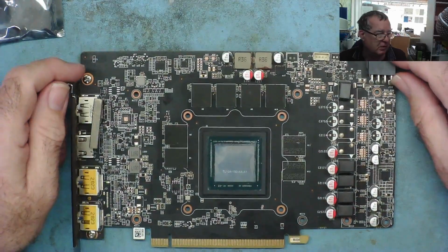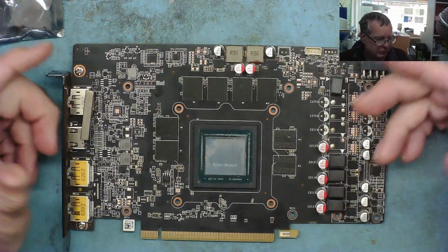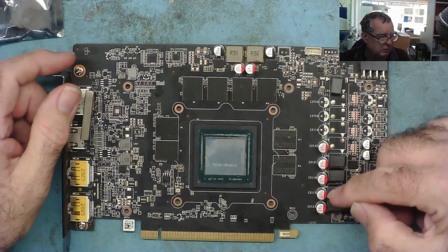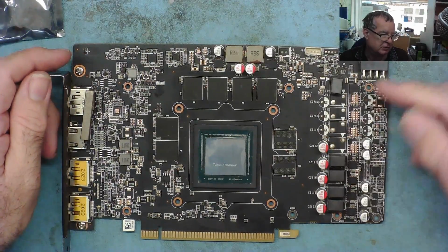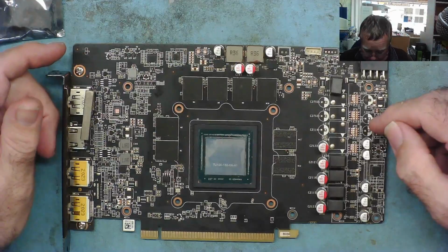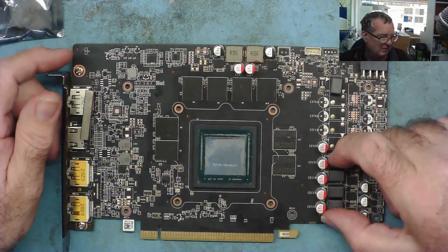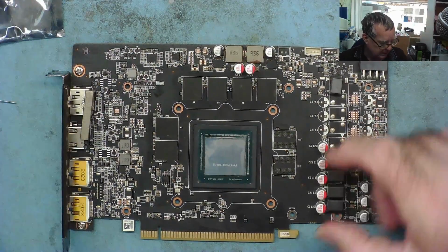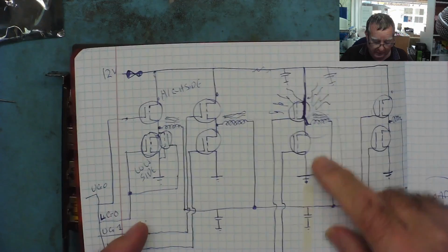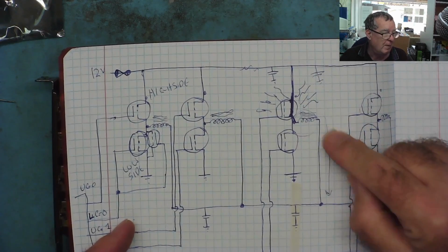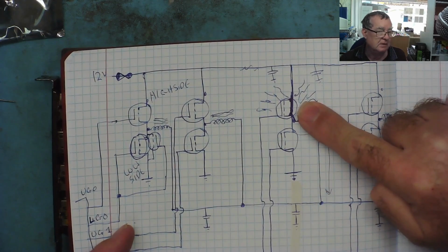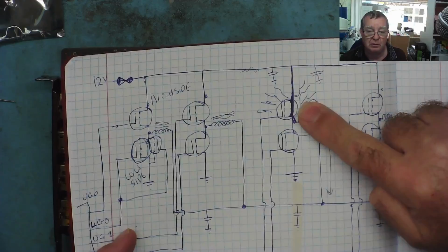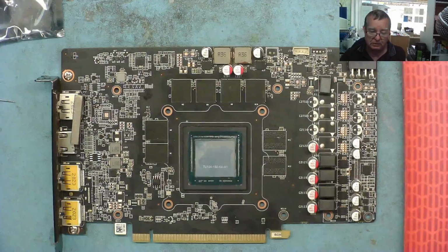Many people ask in the comments to my videos on short circuit finding, if I remove the coils one at a time until the short goes away, will that tell me which MOSFET is short? And the answer to that is yes, clearly that will, because we can see on the diagram, the explanation, that the short is feeding current through a coil, one of them. And if you remove that coil and break the circuit, then yes, that will tell you which high side MOSFET is short.